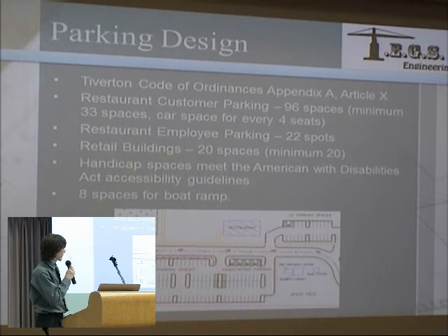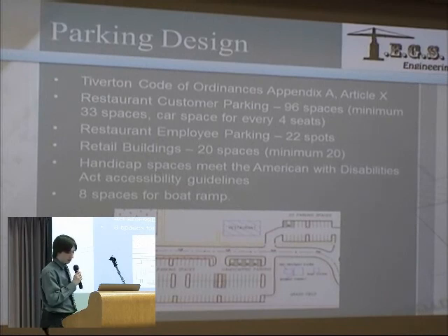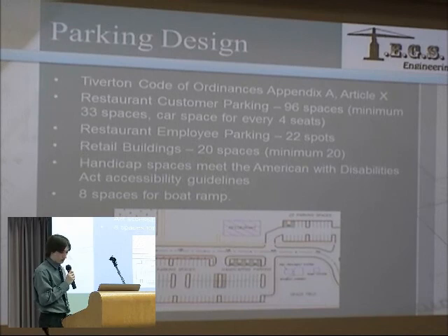We also have 4 handicap spaces. This meets the American with Disabilities Act accessibility guidelines. That states that we need 1 spot for every 25 spaces.